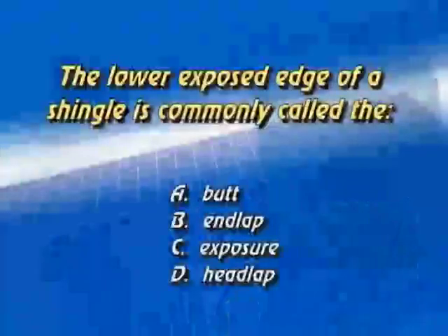Number 46. In general, how many nails are required to fasten a wood shingle or shake? The answer on that is 2, and it's usually 1/2 inch to 1 inch from each edge. Answer is B.